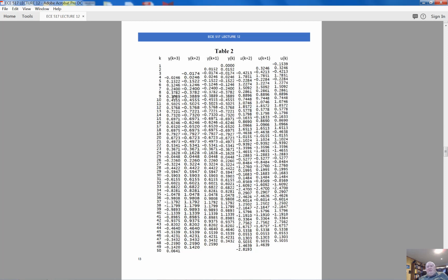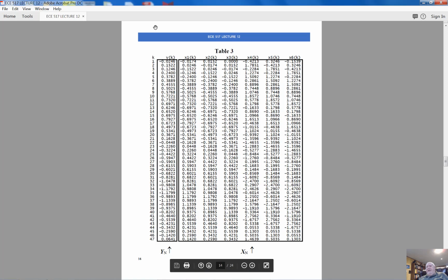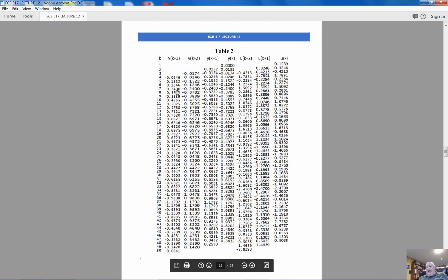Now, if you would follow this part, this part is consistent with the appropriate section of the column for y, for the output. Exactly the same thing. This column is consistent with the input-output data for the output, and so on. Next, I have to lift this column up by 3 positions. This should be lifted up by 2 positions, by 1 position. This should be left alone, and by doing so, I will get an array of output variable y. And then I would perform shifting on these 3 columns, and eventually I will come up with the array representing all input measurements for our system.